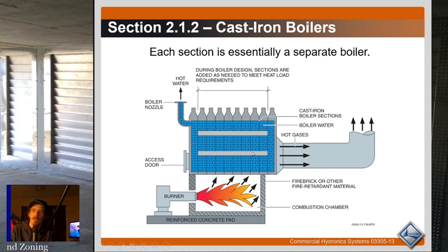and the boiler. And that's the other thing that's nice about boilers as opposed to furnaces, because these things are filled with water, right? And that water is constantly circulating. These things are a lot less likely to have cracks than furnaces, because furnaces just have the air going across, so they overheat, and they tend to be made pretty thin.